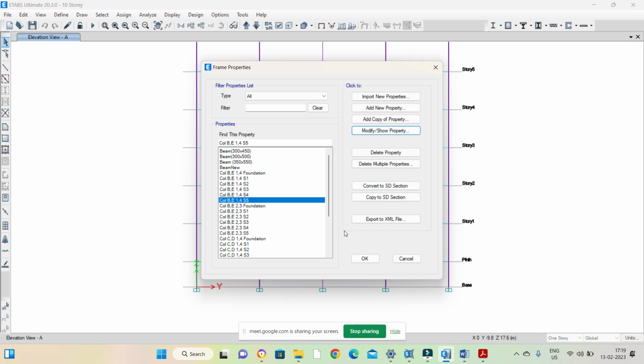For example, the structure is failing, what is going to fail, top column and top beam, right? So it will not affect the performance of the whole structure. But suppose some intermediate story columns are failing, then it will affect the global structural performance, right? So that's why usually we ignore that top story one. It will have the local failure criteria, maybe one column or one beam will fail, so that we can easily repair, right? We can retrofit or we can do the repairing, so that is no problem.